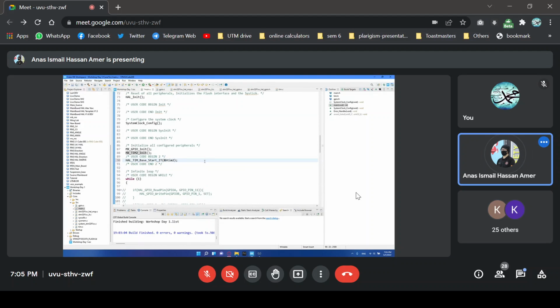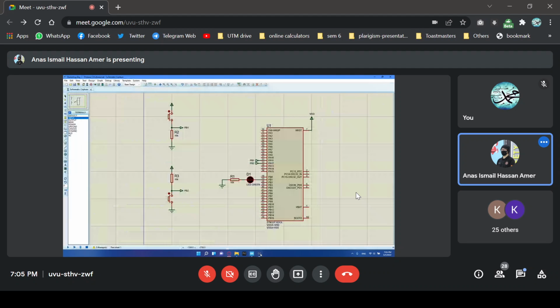So that's it. So now, once it starts and the interrupt starts, the LED will keep blinking. We'll just build again. If we go back, press run, the LED should blink every 200 milliseconds. So again, our main code is now empty. Just the interrupt is in control of this LED. So this is why the interrupt is useful. We can do something repeatedly without interrupting the main program.